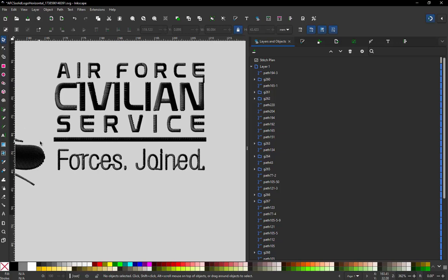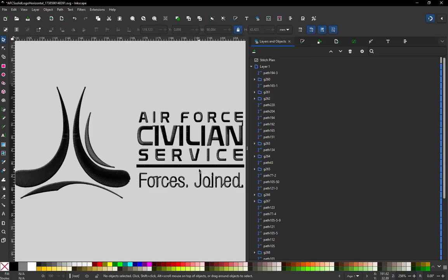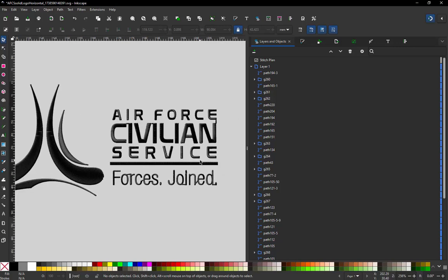Okay, and obviously I would definitely make that piece wider, but then going forward, think about that. I would really encourage you to think about not having elements that are only half a millimeter, maybe have at least 3/4 of a millimeter to a millimeter as your minimum, your baseline. I just feel like you'd have easier results personally. But you play with it a little bit. Try different settings, different density settings.